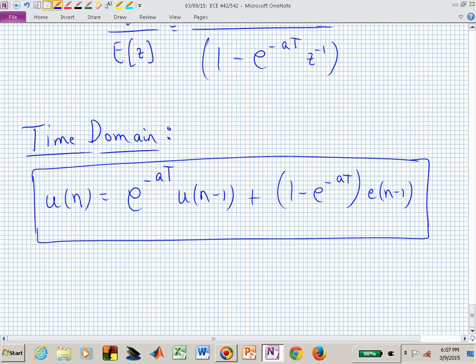on this material? Is it clear now the difference between what you were doing by hand and what MATLAB was giving you, if you've done your homework? And you could make yours agree with MATLAB by saying, I'm going to force a 1 sample period delay between my input and the output, and then your hand work would just have one of those z+1 factors. You would use that to establish your gain, and then your work should be consistent with what MATLAB was producing. Questions on that?